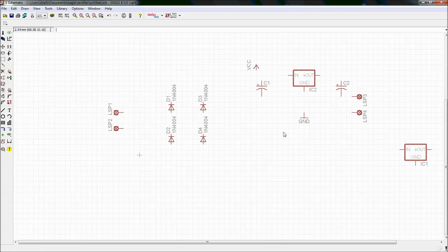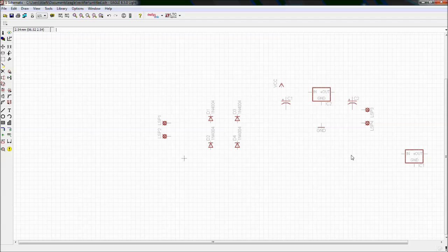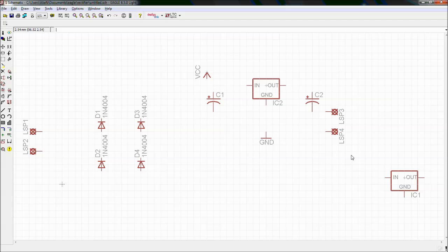Fine. Now for proper visualization, you can see this IC is not visualizing properly, so you can zoom in or zoom out. Otherwise we have a shortcut, Alt F2. Okay, the system will automatically take all the components and properly show you on this canvas. Okay, now I just want to delete this first. Use the delete tool. Fine.